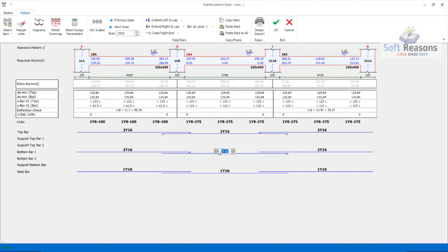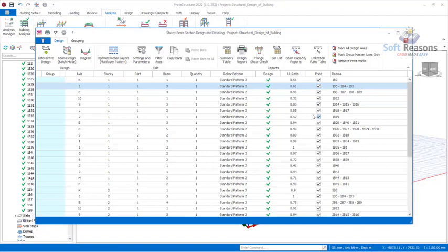So with this, we have to also check the span of the beam. Can increase this to 3, although 2 has passed, but just increase this to 3. Reinforcement bottom, because this is 4.7 meters. Can also have 3 top and bottom right here. Okay, so this is the interactive design I'm doing. So this is what you are supposed to do to all of the beams, okay, before you produce your drawing successfully. Click on the OK option.